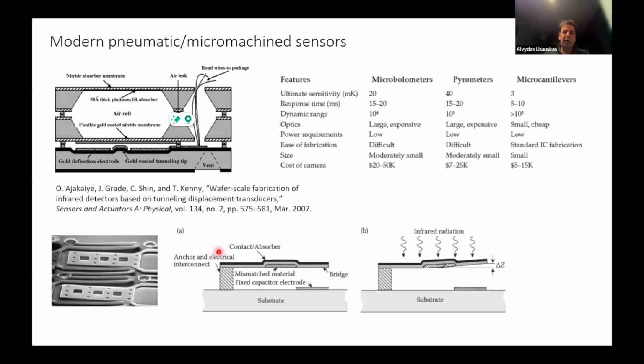It has the same thermal limits, enthalpy fluctuations, which I addressed at the very beginning for bolometers, and there are different ways to get the ultimate sensitivity, or NEPs, and one can create a big variety of microbolometer cameras.